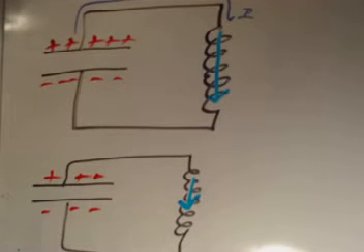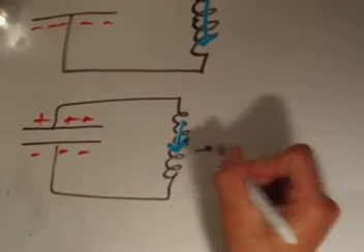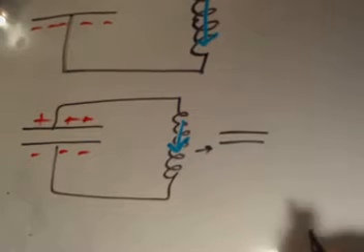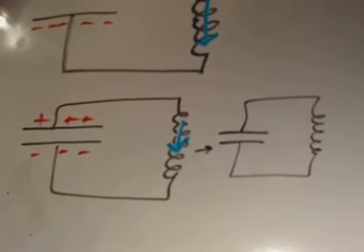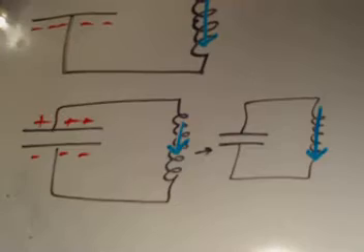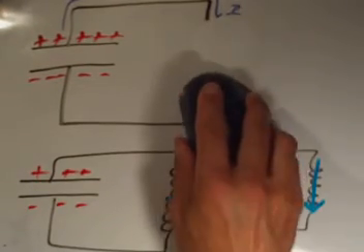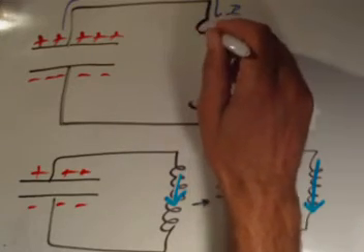And then maybe a little bit more time goes by, and if you leave the two connected like this, you'll have a system that looks like this, where the capacitor is completely empty because it's used up all of its charge, and the inductor is sitting here with this huge magnetic field in it that looks like this. So this is sort of the sequence that will happen here. And I think to make it a little more complete, I'll just remove that one there.